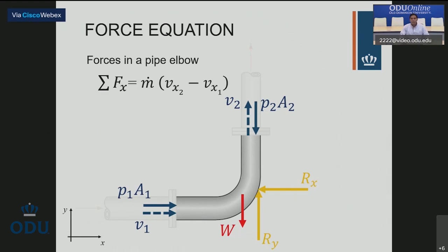And now I have all my forces. Now that I know all my forces, I can make use of my equation. And let's do it. So look at this. What is Bx2? This is the velocity at 2 right here, but its x component. As you could see, this velocity goes along the y direction. It does not have any value in the x direction, so it's not moving horizontally. B2 moves vertically, doesn't move horizontal. So, because it doesn't move horizontal, this guy has to be 0.